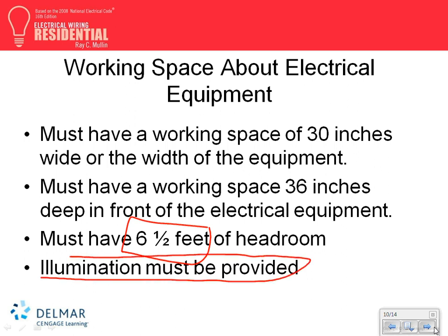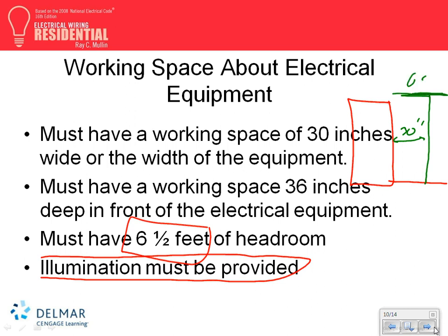You have to have illumination in front of the panel. Let's just go here. This is my panel, 379. If this is my panel, guys, I have to have 30 inches here. And this is actually the headroom, up to 6.5 feet. All this area, all this space, Spencer, 6.5 feet and 30 inches